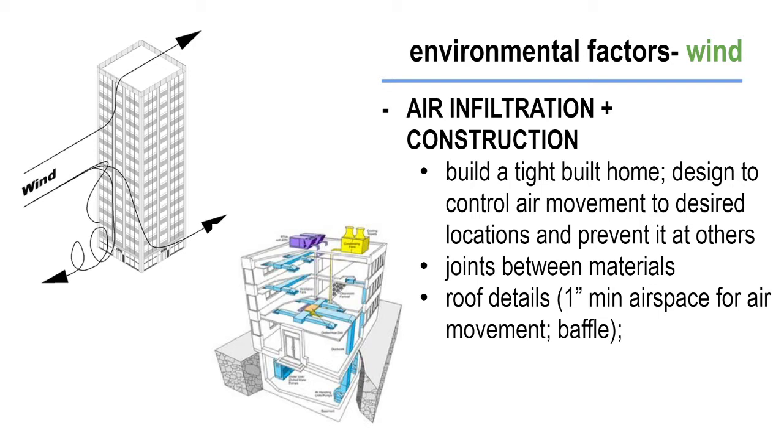In the winter, we have the opposite. We have the cool air enter through the bottom of the house, and it then warms up and pushes hot air out through the top. That's what's called the stack effect, your air constantly moving, trying to reach its equilibrium. The more we can seal that building off, the less we have to worry about that effect. Hopefully I've said that enough. I've probably said it about 1,500 times so far.